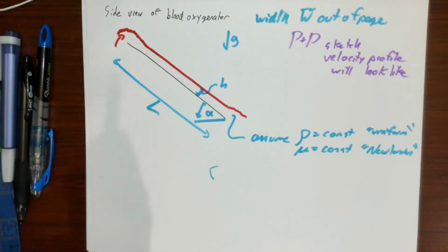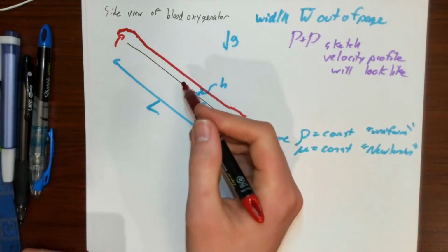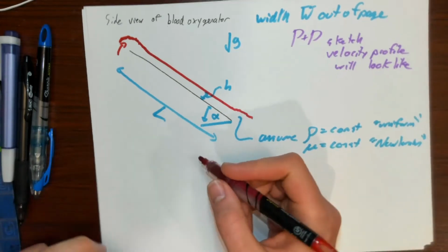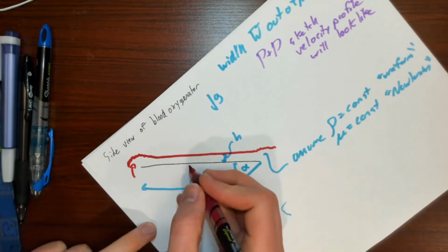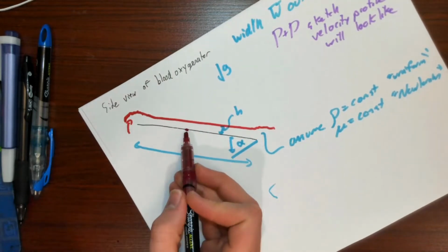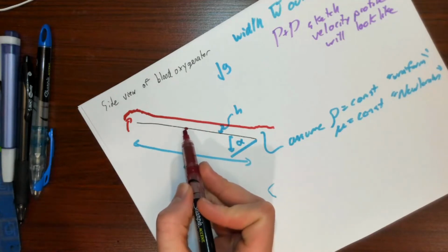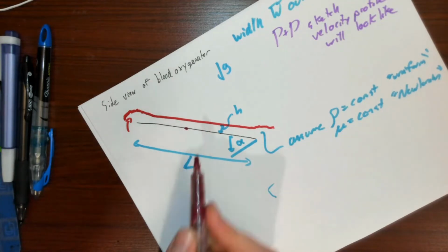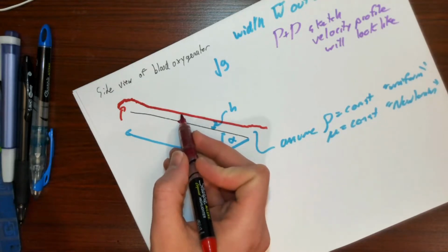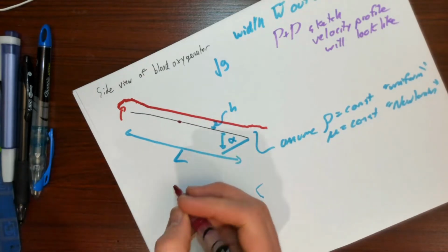All right, hopefully you've had a chance to pause and ponder. I'm going to do the annoying thing where the professor already knows the answer, so we can sketch it out very easily. So we anticipate the velocity being 0 right at the surface here, because the ramp isn't moving, so the fluid immediately adjacent to the ramp is not going to be moving. And we expect that the farther we go away from the ramp, the faster the fluid is going to get.